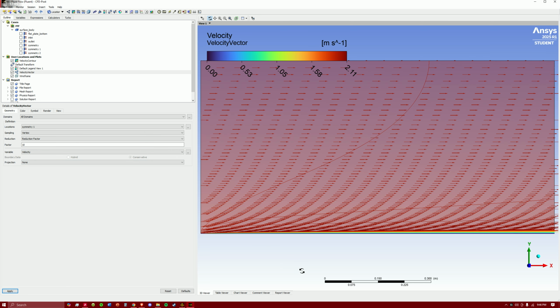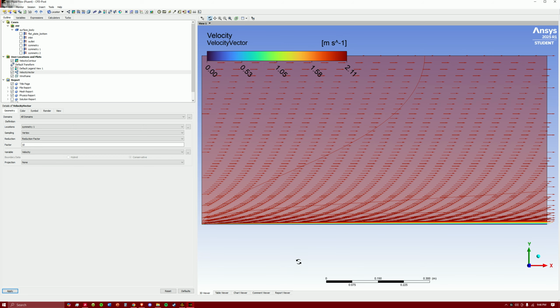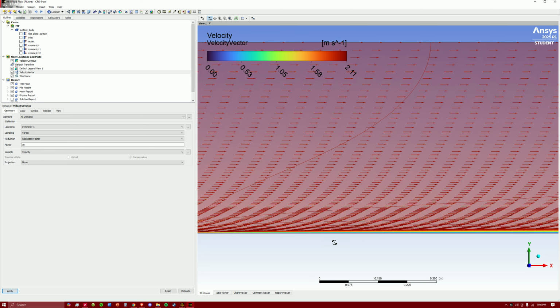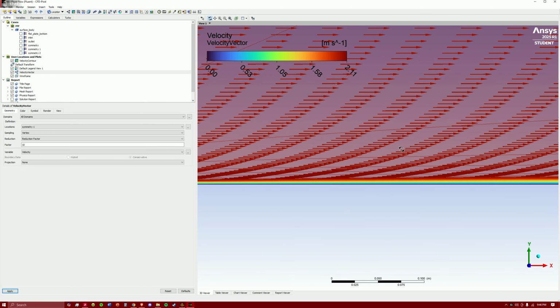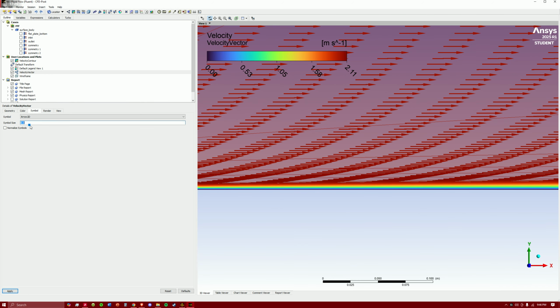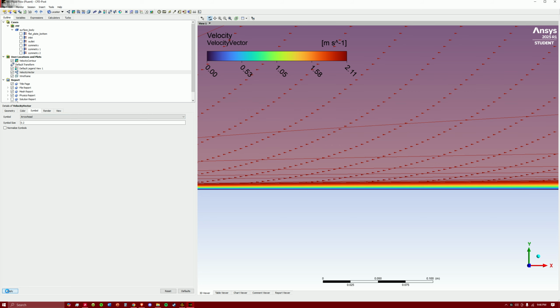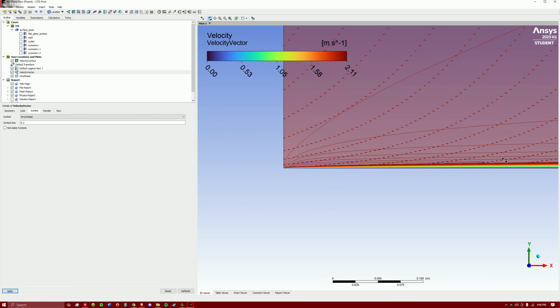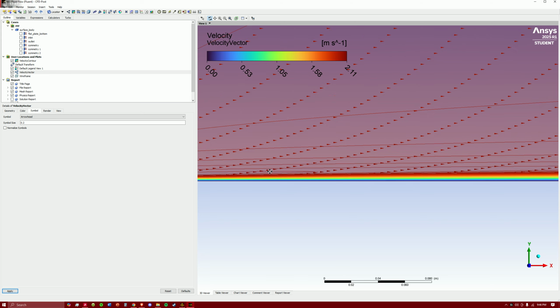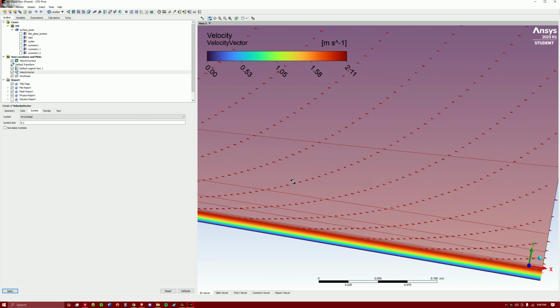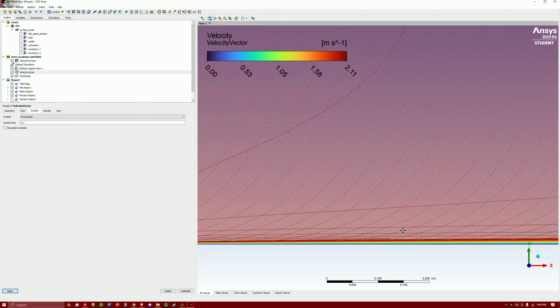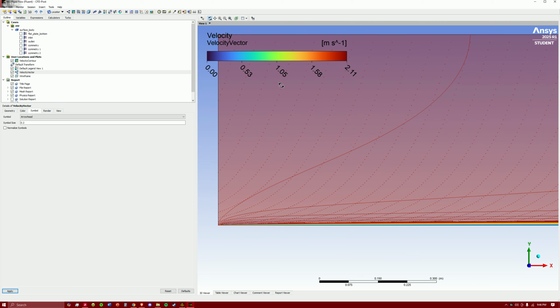Would you look at that? Can you just see that perfect boundary layer develop? Look at these velocity vectors, or vector velocity profiles. You can literally see it within the vectors. This is beauty. I mean, it gets a little confusing down here, but if you wanted to, drop this down, 0.2. Maybe arrowhead. How's arrowhead look? That's perfect. Now you can actually see your velocity profiles. So that right there, screenshot. Maybe not from here, whatever.